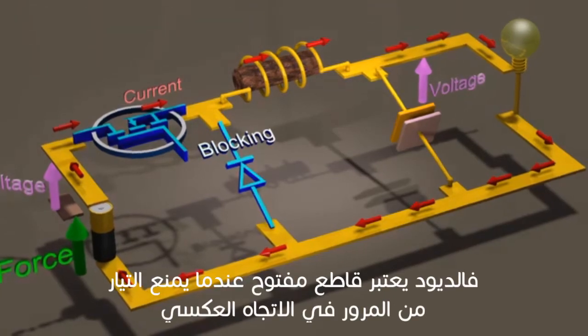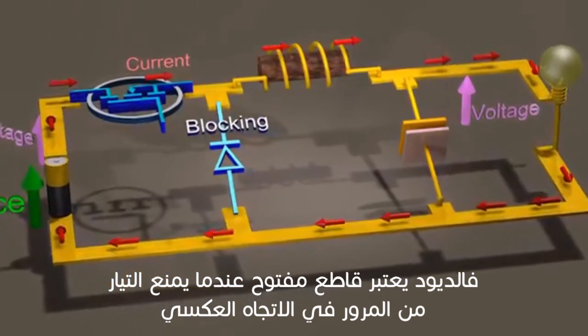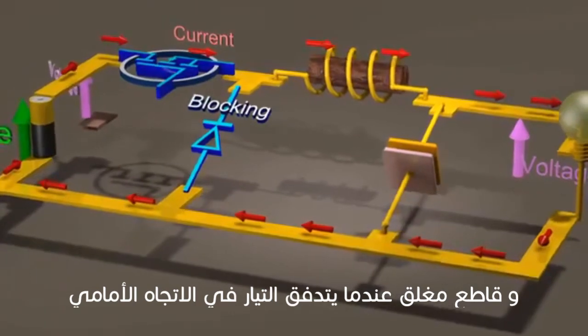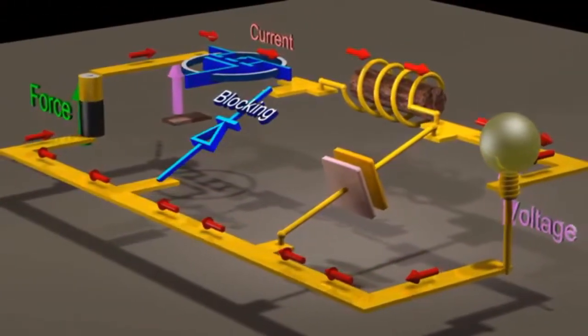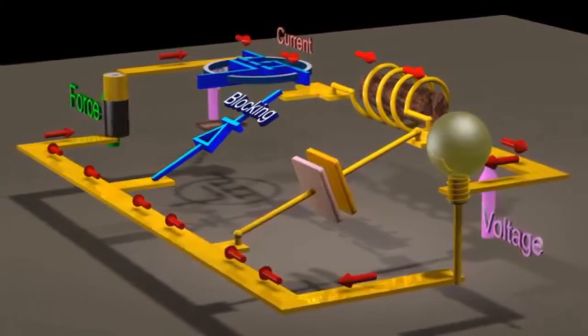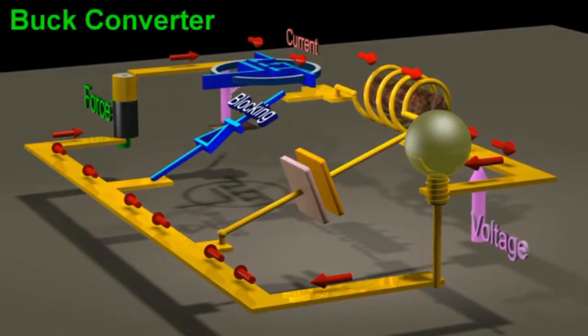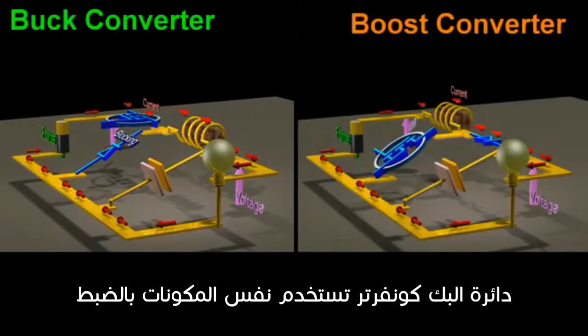The diode is an off switch when it is blocking current from flowing in the reverse direction, and the diode is an on switch when current flows in the forward direction. The buck converter uses the exact same components as the boost converter, just arranged differently.